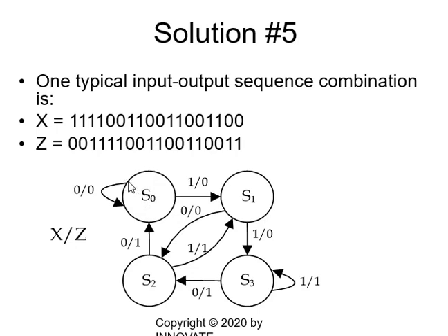If I receive a 0, I will remain in S0. If I receive 1, 1, the output will be 0, 0. Then I receive 0, I will go to S2, the output will be 1. If I receive another 0, the output will be 1. So this will be a delay by 2 clock cycles. So 1, 1, 0, 0 will give me 0, 0, 1, 1.